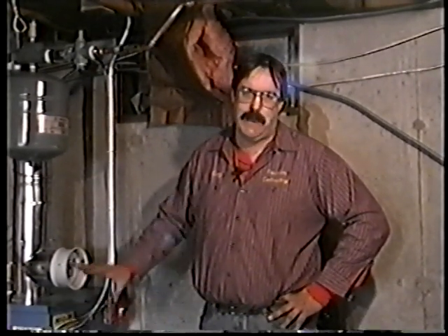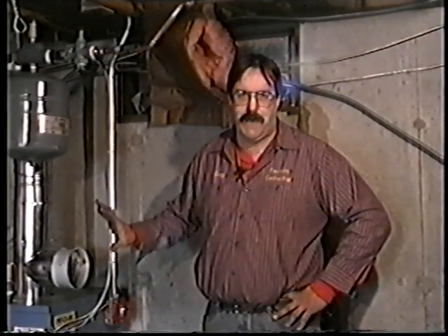If you do see signs of a house that was not de-winterized, you should definitely call a contractor, have them look at the heating plant, the heating system, and make sure that everything is in good working order, because as fast as the pipes freeze and burst, the same thing happens to these types of heating systems. They freeze up just as fast, and the boilers will burst, and you won't know that until you go to fill it up and turn it on.